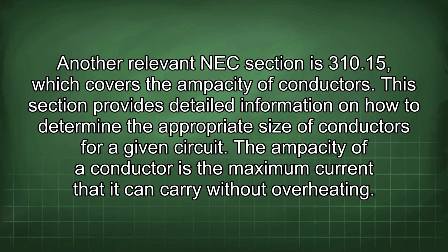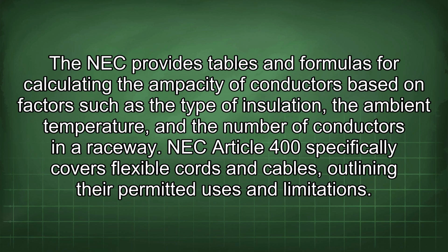Another relevant NEC section is 310.15, which covers the ampacity of conductors. This section provides detailed information on how to determine the appropriate size of conductors for a given circuit. The ampacity of a conductor is the maximum current that it can carry without overheating. The NEC provides tables and formulas for calculating the ampacity of conductors based on factors such as the type of insulation, the ambient temperature, and the number of conductors in a raceway.